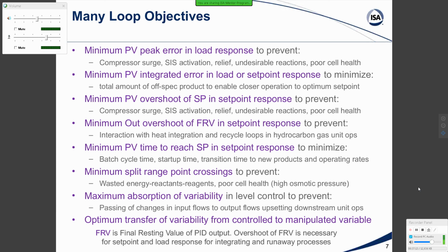Now, you will see variability disappear in the process variable as a result of the attenuation action that you get from backmixed volumes that smooth out the oscillation. So, yes, the process can reduce what you see as variability, but that depends upon having volumes that have some mixing going on, so that these volumes act like a filter. If you're coming from an electronic world, it's that residence time and that volume that's got mixing that is the filter time constant. And so if you have oscillations going on, that filter time constant can attenuate them, and so you don't see them.